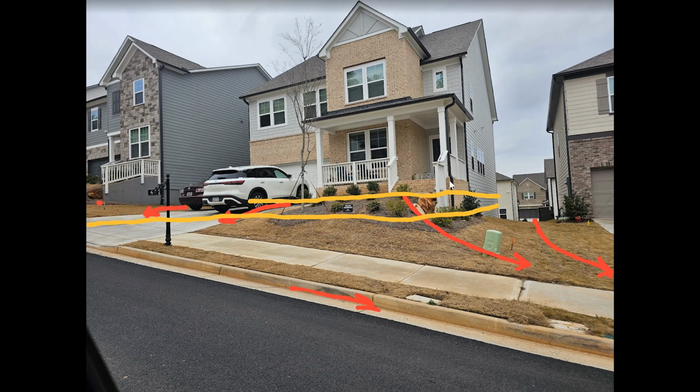But again, we're not going to draw those contours once they hit the building. We can pretty much end those where they're at. And just showing where that brick wall is ending, but as I look at it a little bit closer, that is actually extended out with those rocks a little bit more. And the rocks act sort of like a wing wall.